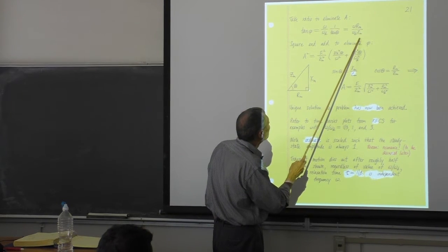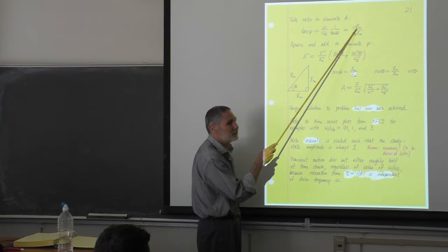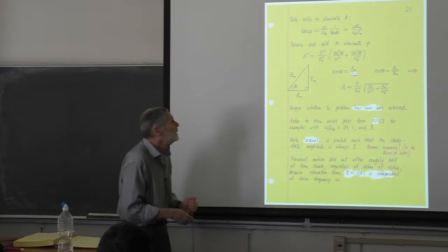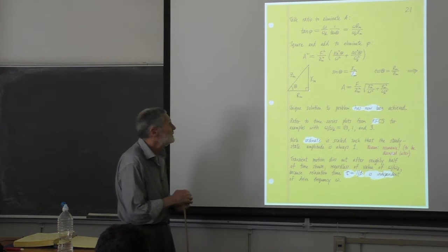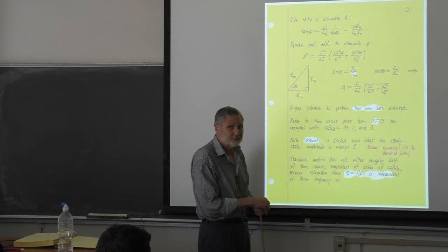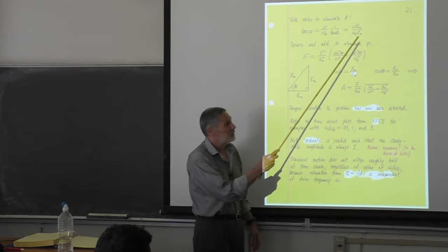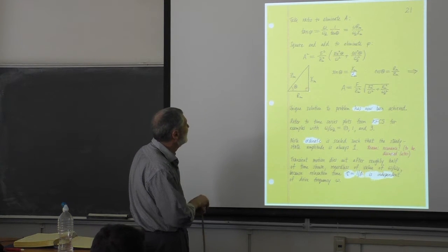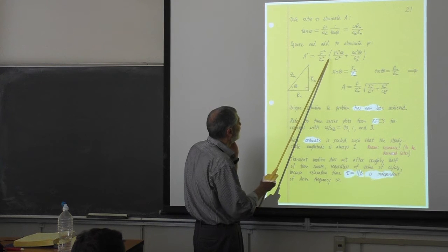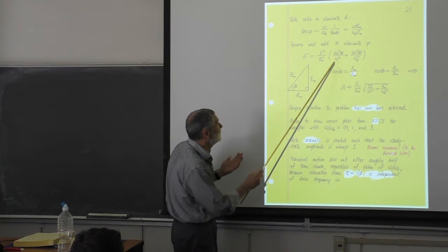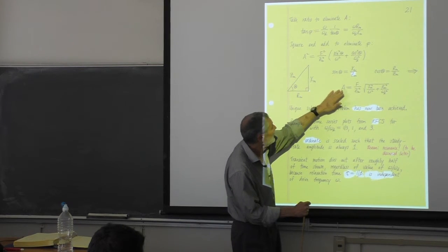They're buried in here, right? This is a fundamental parameter, or closely related to it. Yeah, this is a fundamental parameter of our oscillation system, our oscillator here, because it's the dissipation factor. Because we're assuming a velocity resistance here, right? So that's fundamental. And we know we can get this in terms of parameters of the oscillator. Okay, and here's the amplitude. Here's what we get when we do what I mentioned before. We get this expression. And now, again, we can eliminate the phase angle of the complex impedance from this diagram, and we get this.